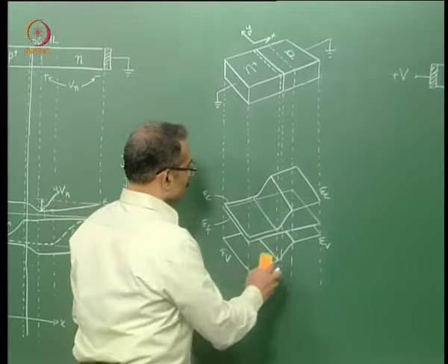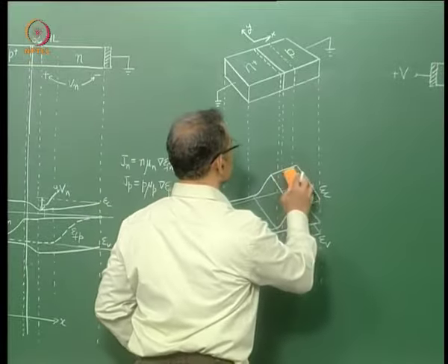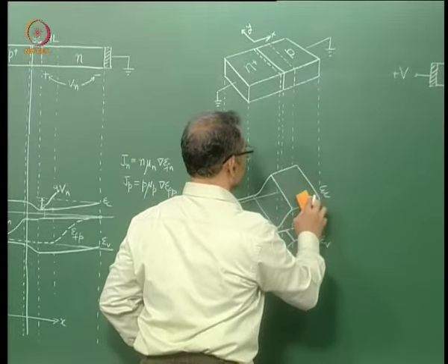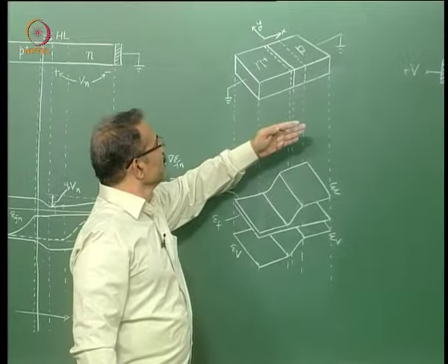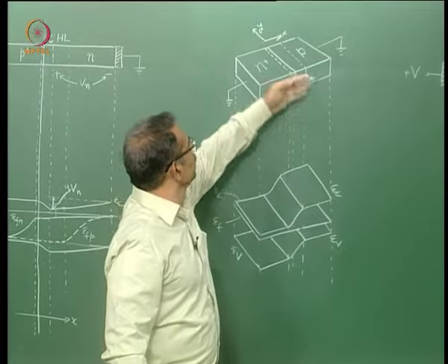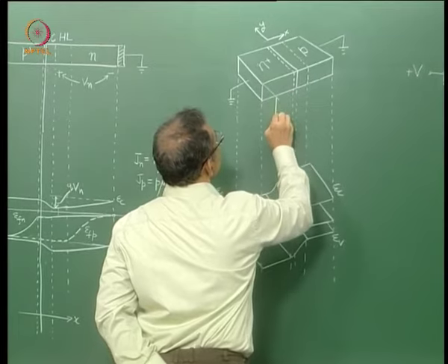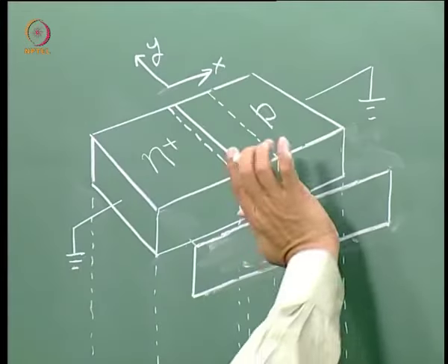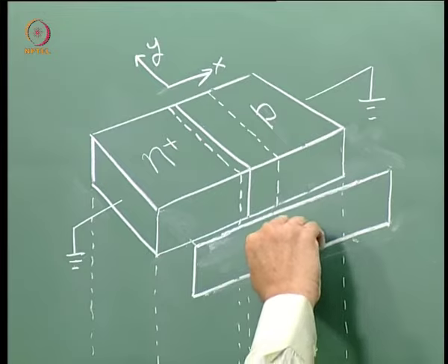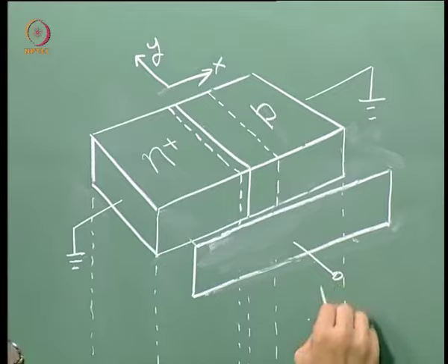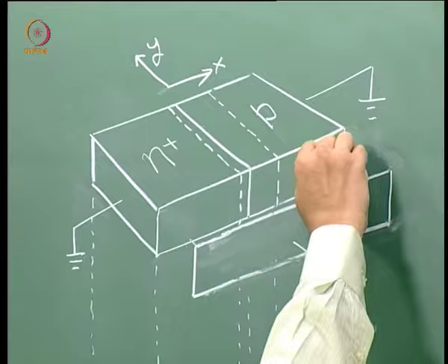Now let me clear up some of the things that are cluttering the diagram so that you can see the two-dimensional band diagram clearly. Now let us apply a gate electrode. We will apply an electric field from this side to the surface. So this is an electrode that is applying an electric field. So it sets up an electric field like this.